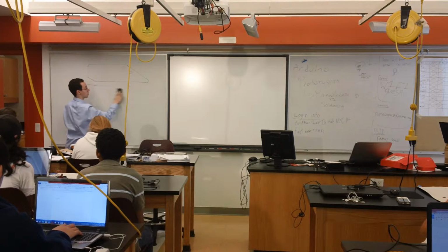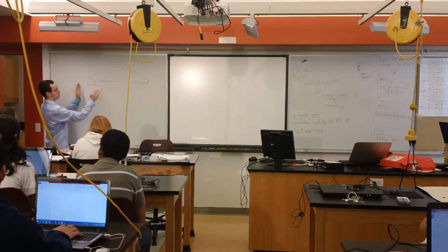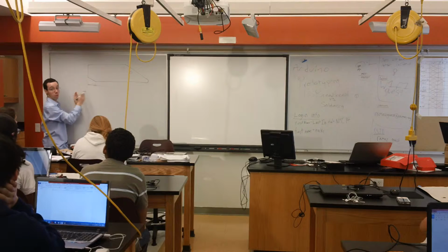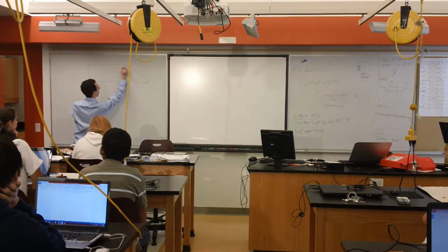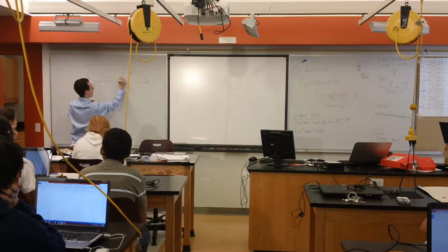So I put these dimensions next to each other in a chain so that you kind of read from left to right or from top to bottom or whatever, and you see where every feature is relative to the last one. So in this case what I do is, okay, I put my center line here in my circle, and I say, okay.